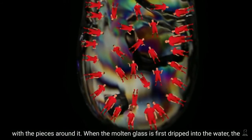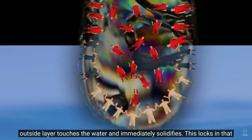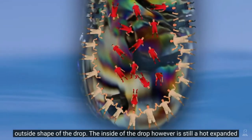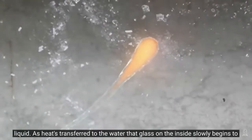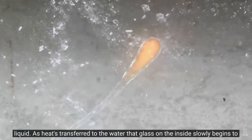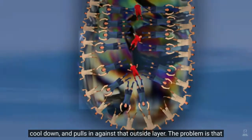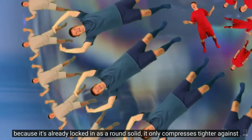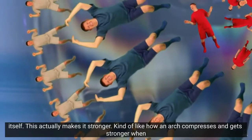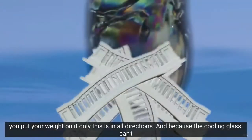When the molten glass is first dripped into the water, the outside layer touches the water and immediately solidifies. This locks in that outside shape of the drop. The inside of the drop, however, is still a hot expanded liquid. As heat's transferred to the water, that glass on the inside slowly begins to cool down and pulls in against that outside layer. The problem is that because it's already locked in as a round solid, it only compresses tighter against itself. This actually makes it stronger, kind of like how an arch compresses and gets stronger when you put your weight on it, only this is in all directions.